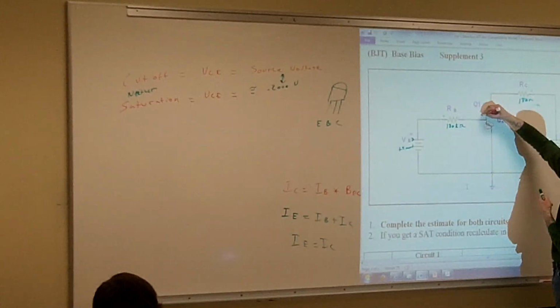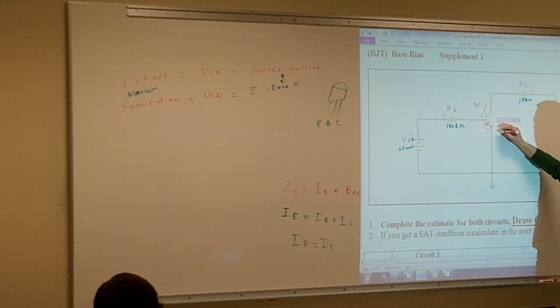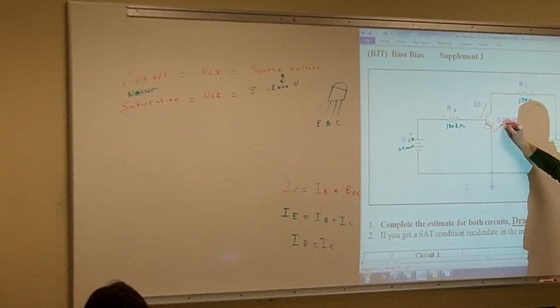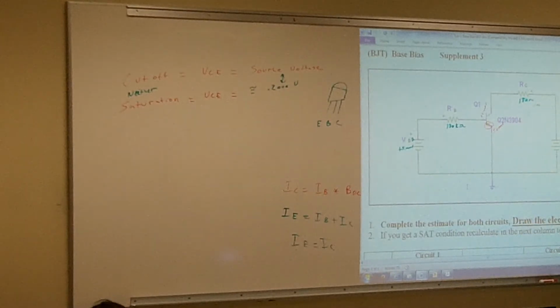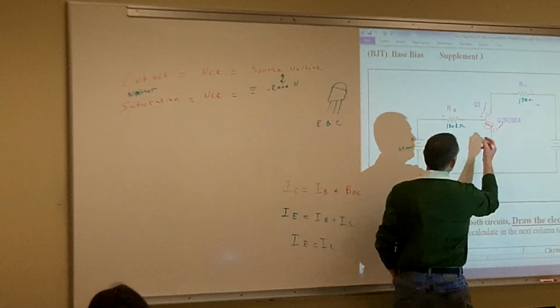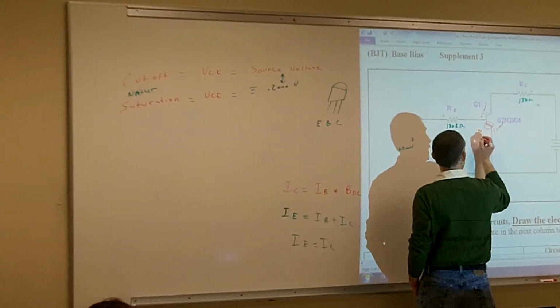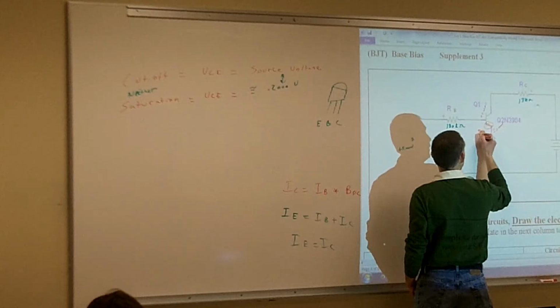Plus 5 volts. And on my cathode side, yeah, plus or minus 0 volts. Okay? So my base emitter, is that going to be a go or no go? It'll be a go. And it's going to drop its voltage, and it's going to drop what for voltage? 0.7 volts.